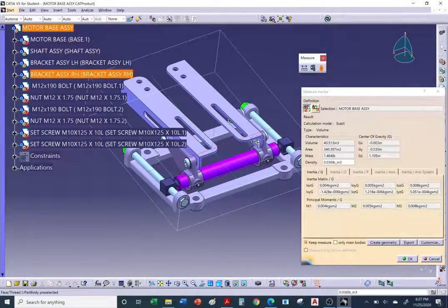I'm going to make it all steel. Okay, and steel has a density of 0.283 or 0.284 pounds per little cube, 1 inch by 1 inch by 1 inch. So one little cube of 1 inch by 1 inch by 1 inch of steel weighs 0.283 pounds. Okay, so I'm going to type in 0.283 or 0.284.